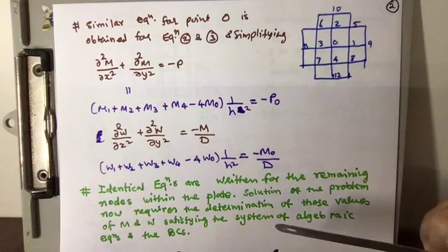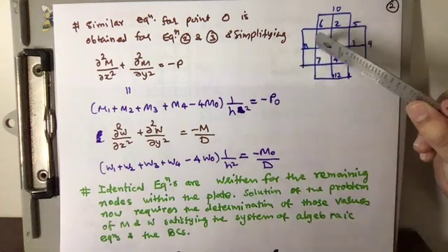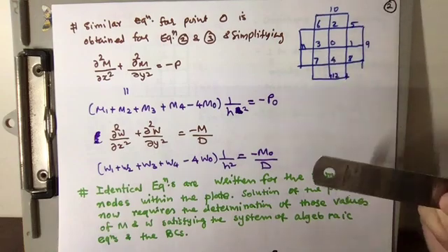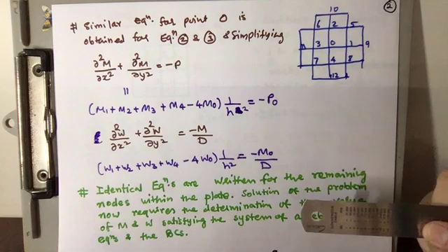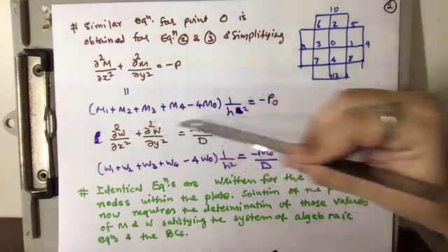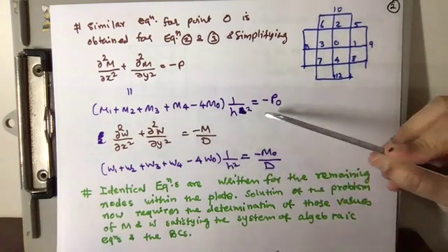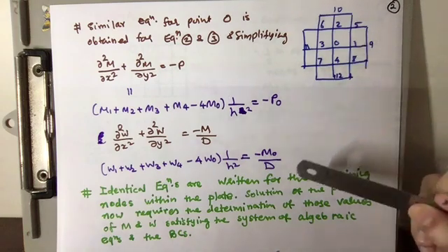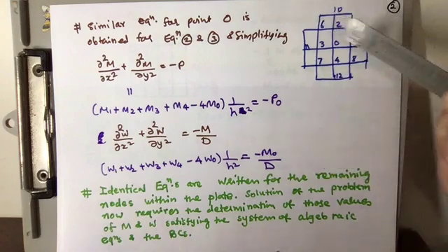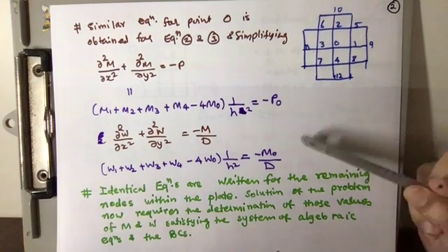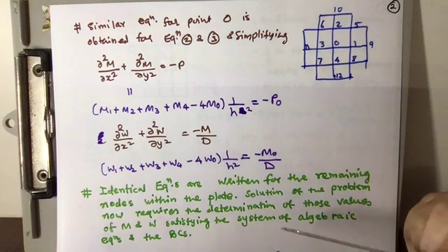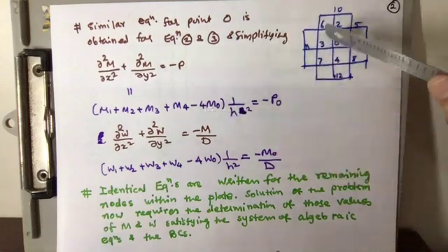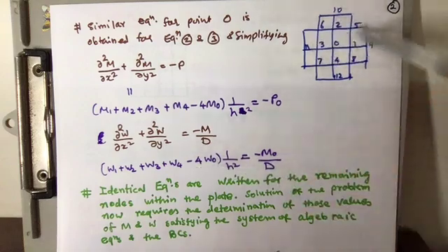Now to get the solution, we can write this equation at each and every node or point, and in the entire process, we'll get simultaneous algebraic equations similar to these. This is one equation written at point O, and similar to this we can get the similar equation at every other node, and we will get as many simultaneous equations as the number of nodes, unless some symmetry condition is applied, that we will see later on. And the solution of these simultaneous algebraic equations gives us the values of moment at the nodal points and the values of deflection at the nodal points.